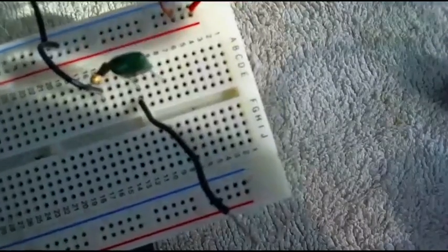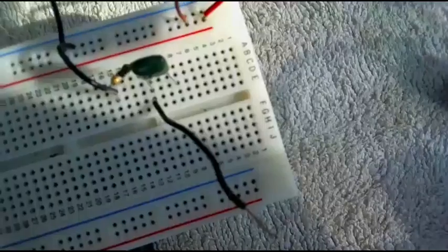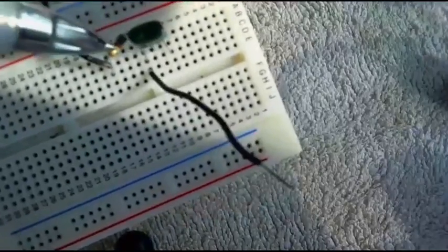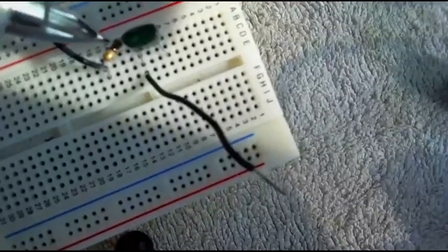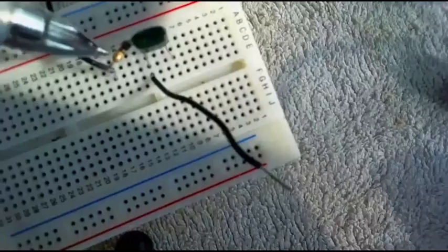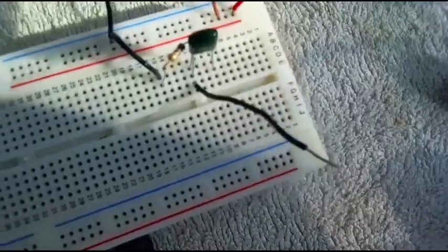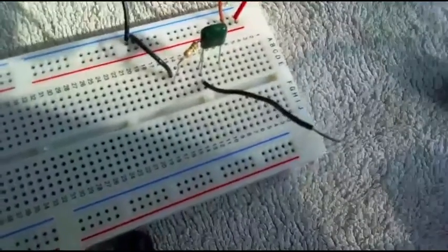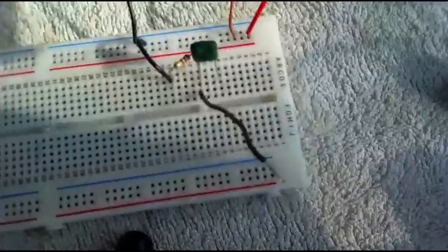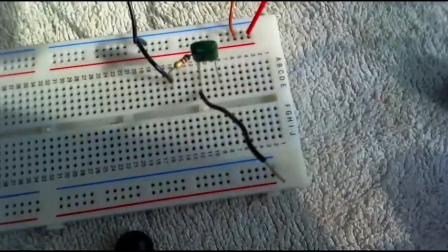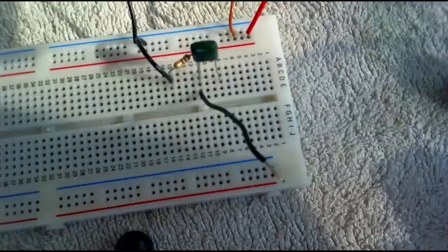to compare the voltage signal as I scan frequency over the whole circuit to the voltage drop over my resistor. And I'm going to use that to help me identify the resonance frequencies. And for that, I'm going to use 2 functions on my oscilloscope, the scope and the spectrum analyzer. I'm going to start with the spectrum analyzer and sweep across different frequencies. And I'm going to use that to dial in a rough estimate of where I'm going to find resonance.